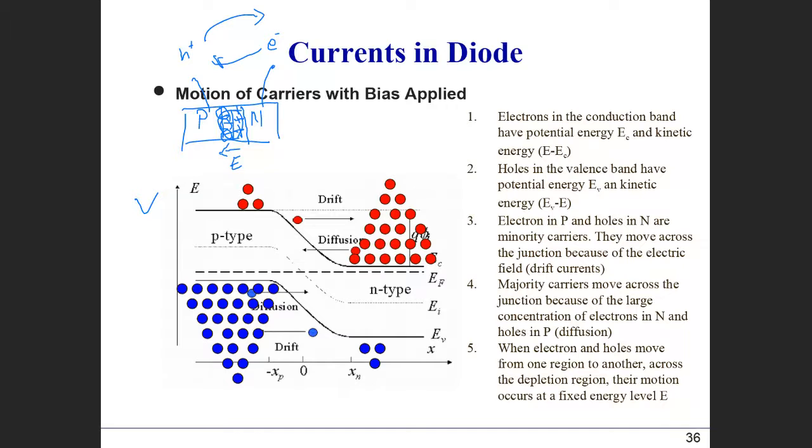Now, on top of this energy band diagram, I just drew graphically the distribution of the electrons and holes. For example, in the n-type semiconductor, as you know, we have lots of electrons available at the top of the conduction band. So roughly I drew the number of electrons with these red dots here. Most of the electrons remain close to the conduction band, and when we go up from the conduction band, the number of electrons is going to be smaller. So roughly we can describe the distribution of electrons in this way.